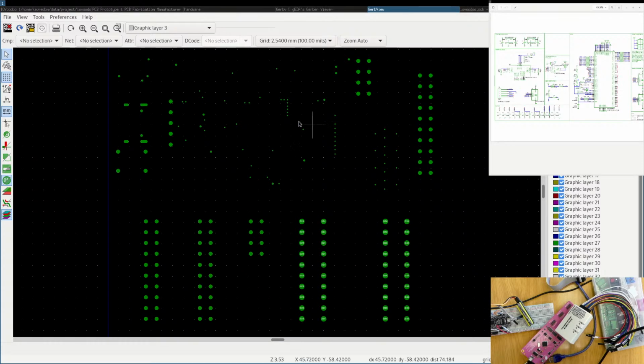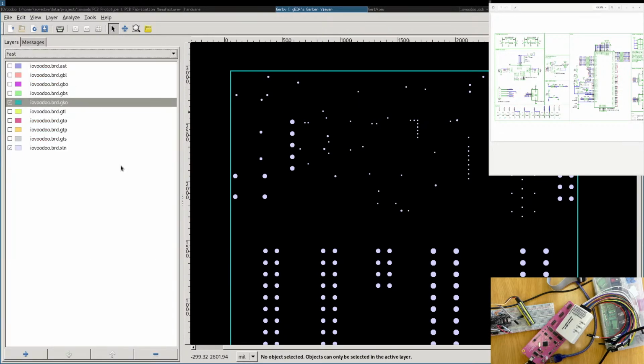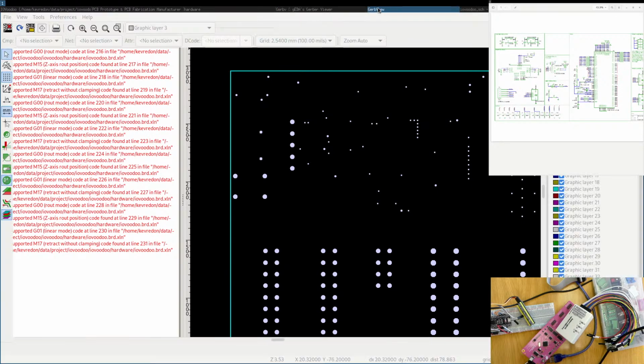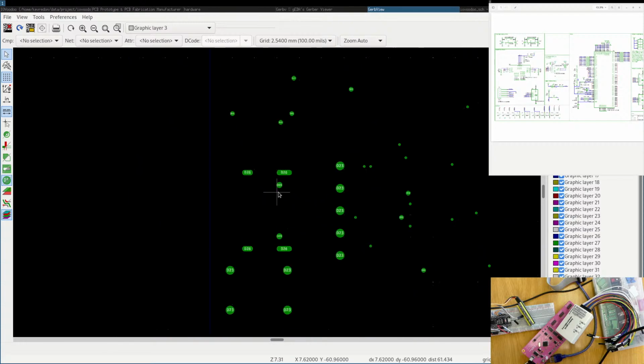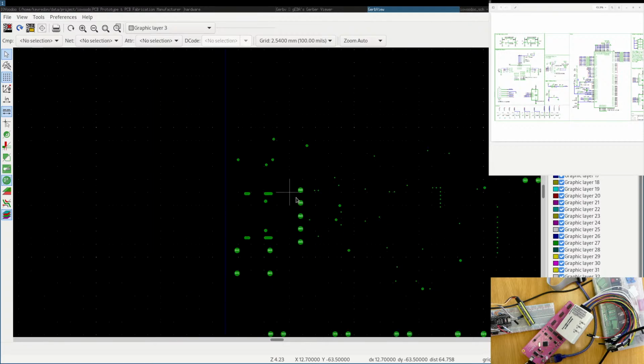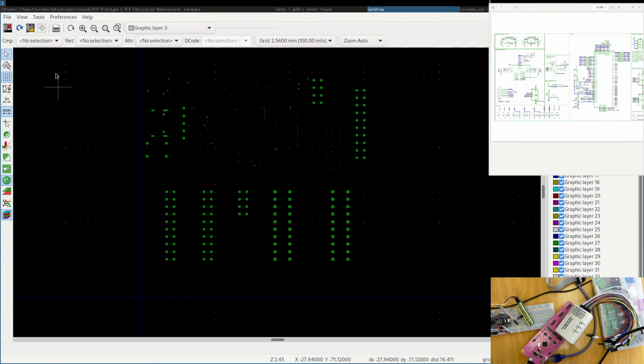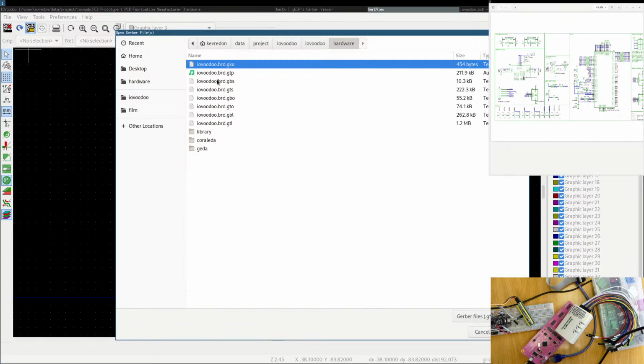Okay. And you see, it really depends on the program. If you only use Gerbv, which is simple to use, you don't have this slotted. At least it warns you, which is very good. Gerbv does show these slots, D26, D26, D26. I think it stands for diameter 26. But here we have the slotted. Here we have the slots for our connector. So this works nicely.